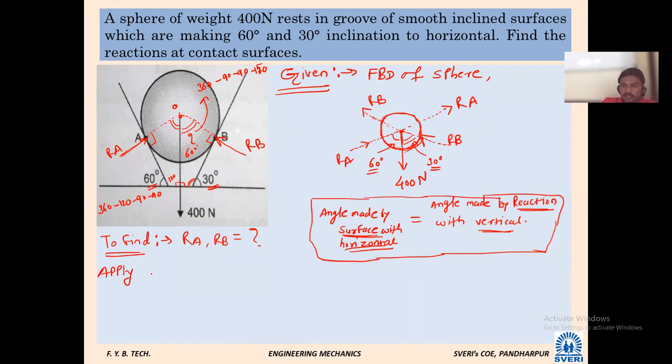How many forces should be there in the system? 3 forces. How should they be? Concurrent. And what is the criterion? They should bring the body into equilibrium. So apply Lami's theorem.